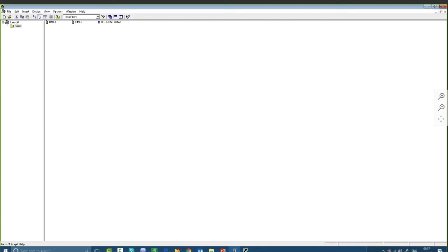How to overcome that problem? Only use a project which has the original settings of that relay. Don't use the running settings on the relay because maybe somebody changed them. Or you can use online, but at that time you have to review all the settings before importing. Otherwise, maybe some error will come and you will not notice it because it's like comparing one to one. For example, if somebody changed the settings and you import the wrong settings into the testing file, then the testing points will be related to those wrong settings.